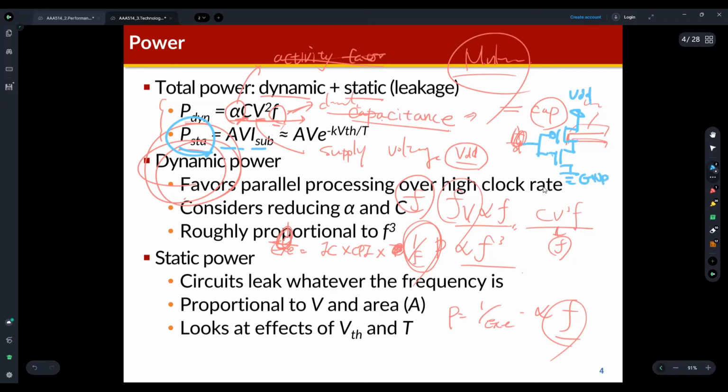So this is the inverter circuit of the CMOS transistor. The CMOS transistor works like a switch. Based on the gate voltage, the PMOS is turned on and off, and the NMOS transistor is turned on and off. Every circuit has parasitic capacitance here, so based on the on and off of these switches, the parasitic capacitance is charged or discharged. That's how CMOS works.